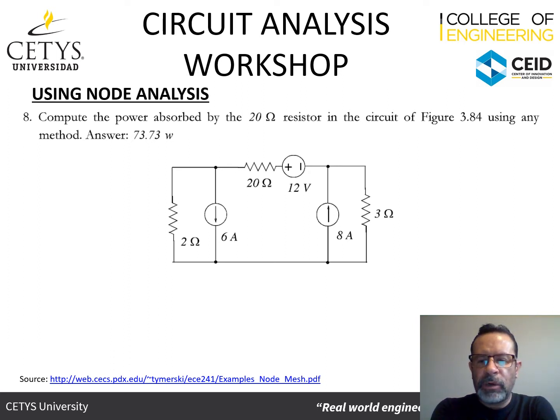Okay, so now we're going to be doing the node analysis of this circuit. Node. It's easier to say than meshes. And so how are we going to do the node analysis for this circuit? Well, first off, we're going to identify the nodes in the circuit. Now, what is a node? A node is going to be a point in the circuit where many things are connected, and these generate branches where the current is going to be divided.